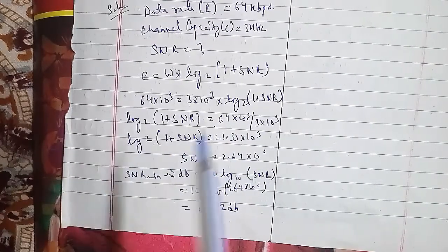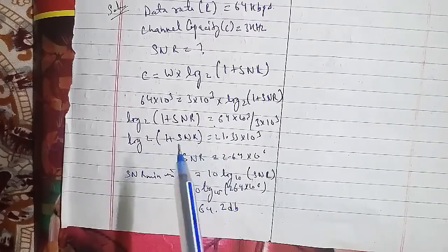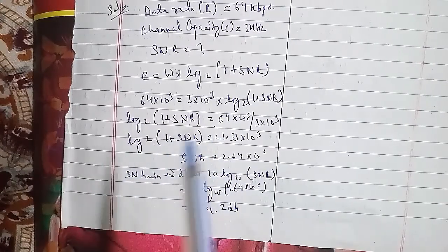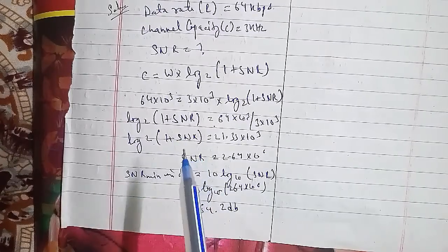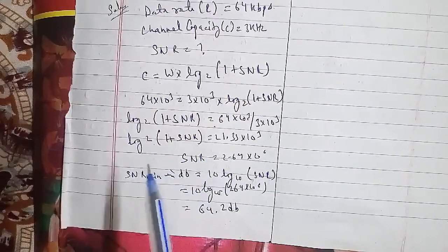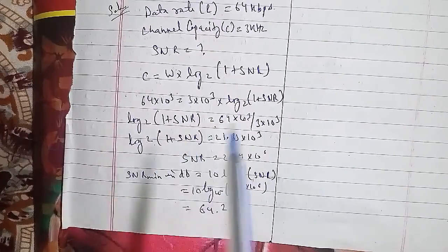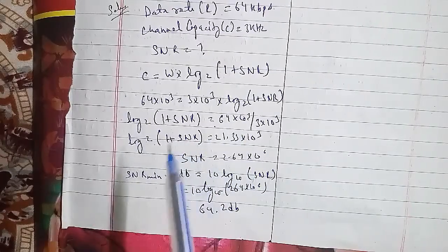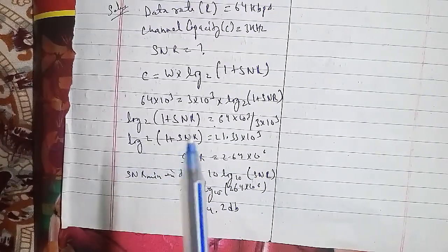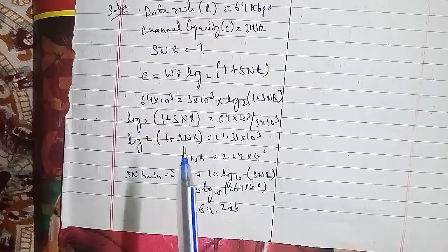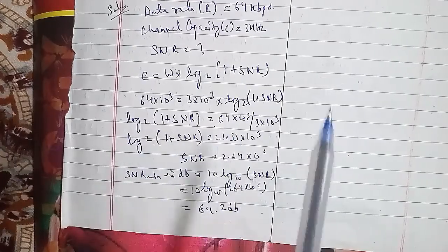The third consideration, known as attenuation distortion, is particularly noticeable for analog signals, because attenuation differs for different frequencies, and the signal is made up of a number of components at different frequencies. The received signal is not only reduced in strength, but also distorted.